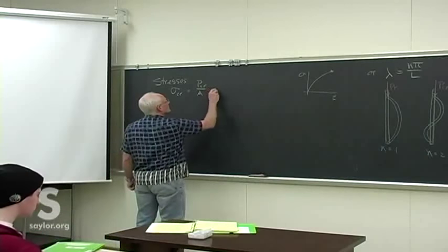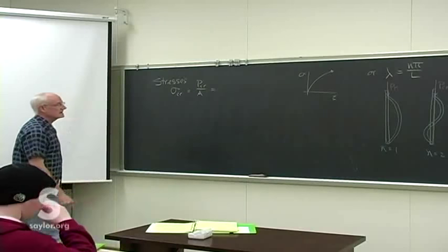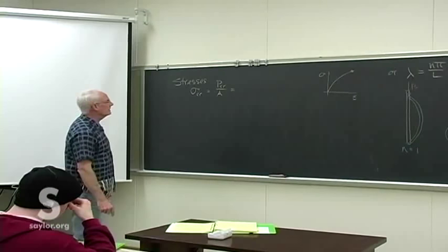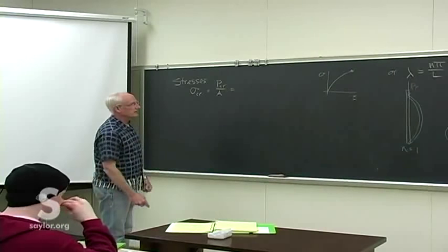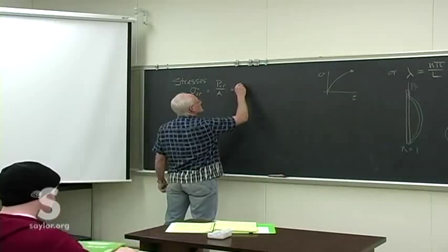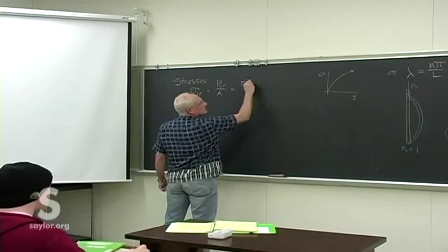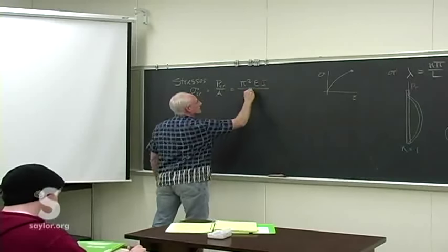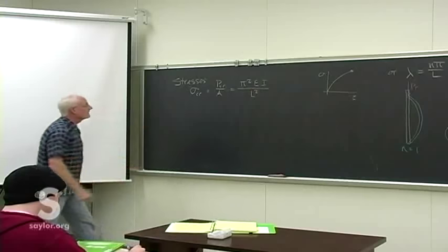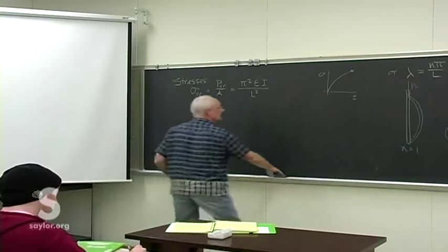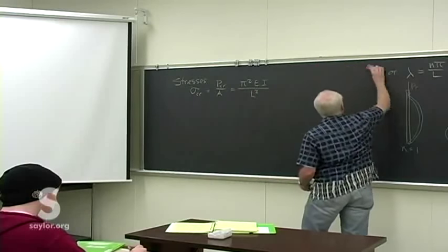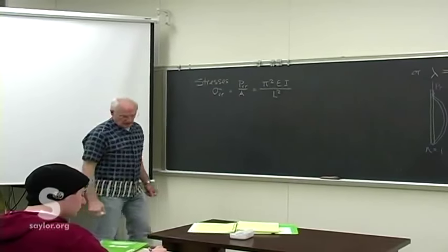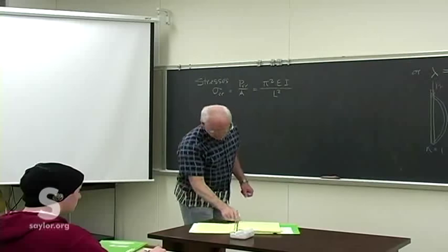All right, so we're going to set n equals to 1 since that's the mode of failure that supports the least critical load. Then we want to find the maximum critical load within that constriction. So we're going to use the limit here on the stresses as something like this. And then there might also be a factor of safety that we'll put in here too, which we actually will do.